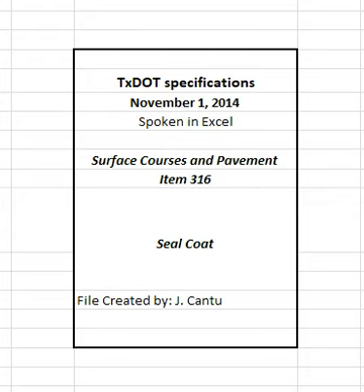When a transverse variable rate is required, and a single spray bar is to be used, perform the test using the type and grade of asphalt material to be used on the project. The engineer may verify the transverse rate and distribution at any time. If verification does not meet the requirements, correct deficiencies, and furnish a new test report. 3.1.3.2 Tank volume.